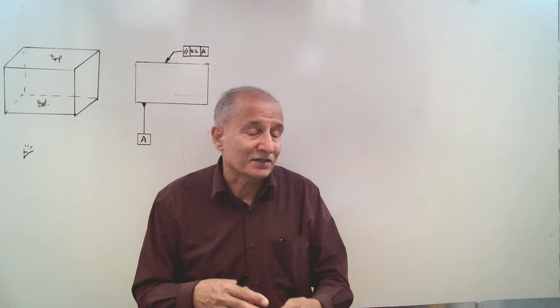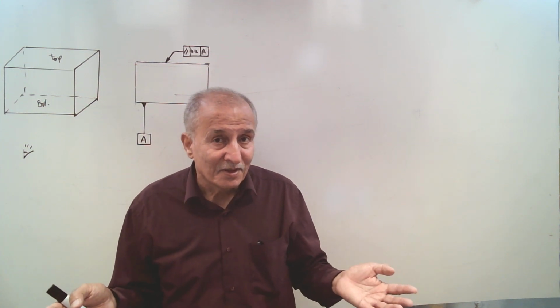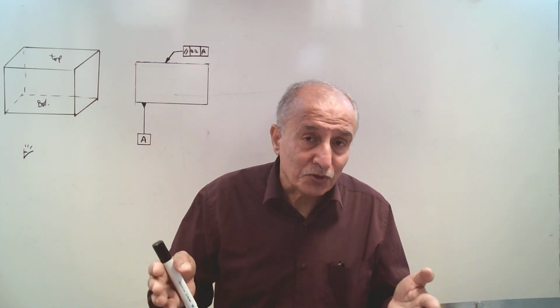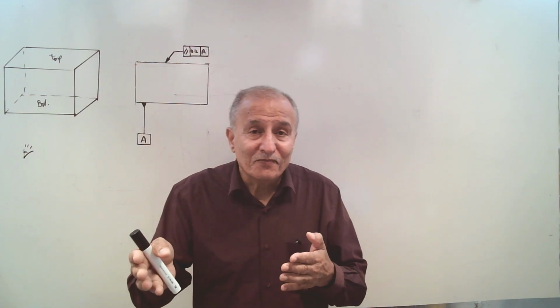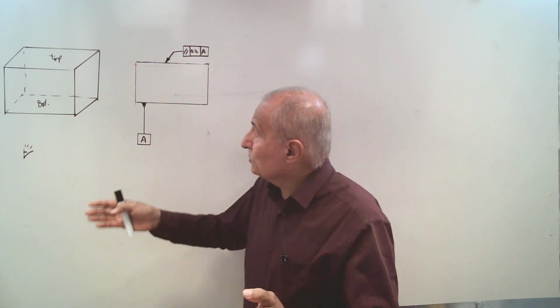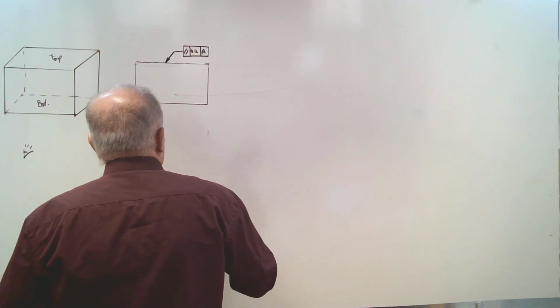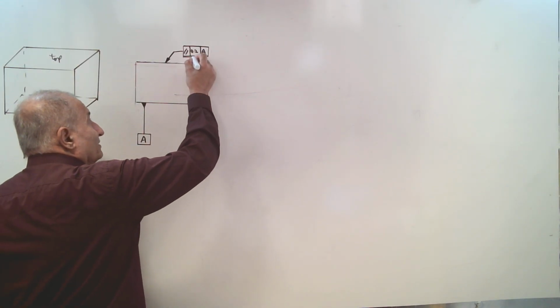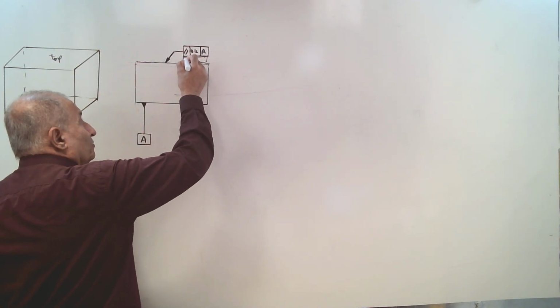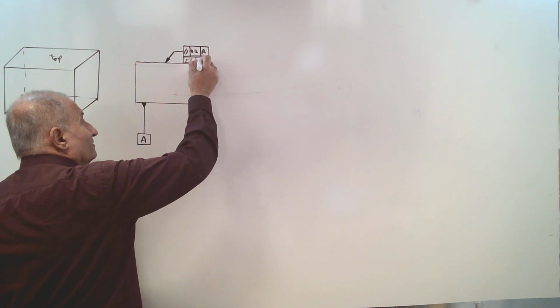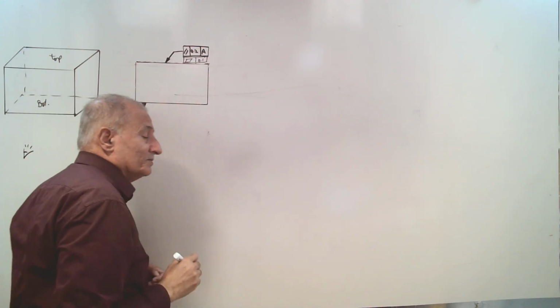Parallelism needs datum. Flatness doesn't need datum. That's the difference. But if you use parallelism and flatness applied to the same surface, both, then this flatness must be a refinement of parallelism. Here you have the flatness as well. For example, point 1.